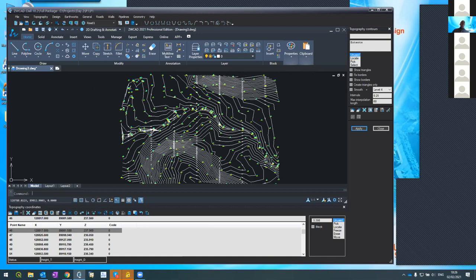There's no such thing as normal, my friends. Normal depends on the survey. For example, if I'm taking an orthophoto and the orthophoto has a grid of 25 by 25, I can define it as 40 to be more accurate. So there's no such thing. I usually start at 50, 60. There are some surveyors around here, so maybe they want to say, but there's no such thing.